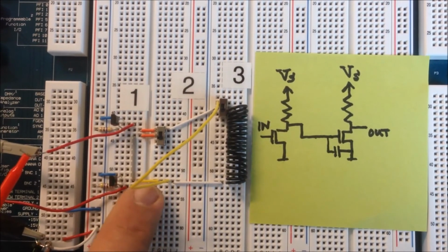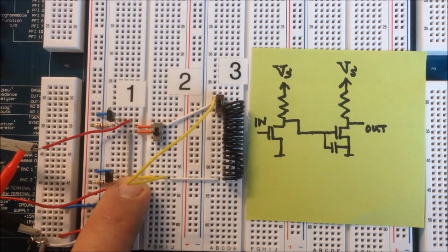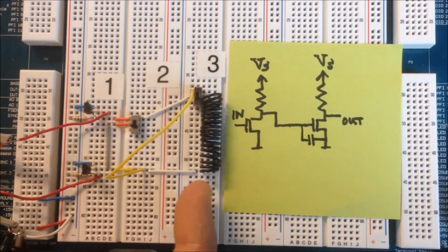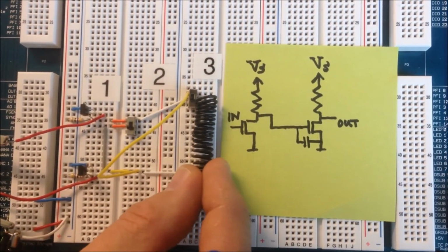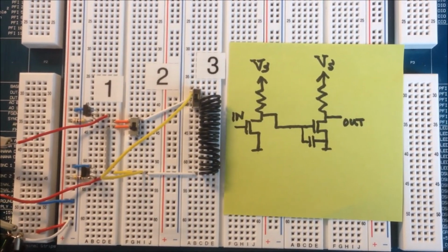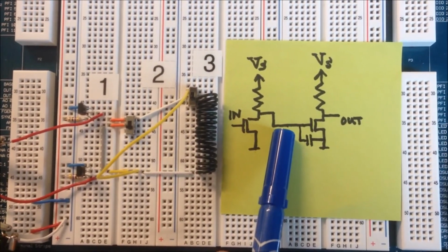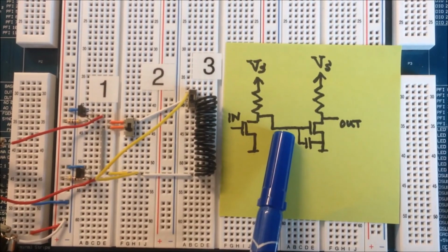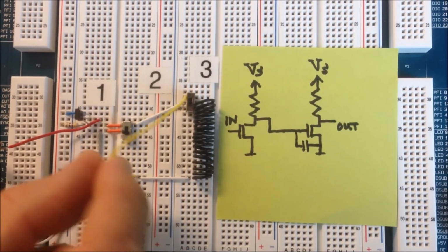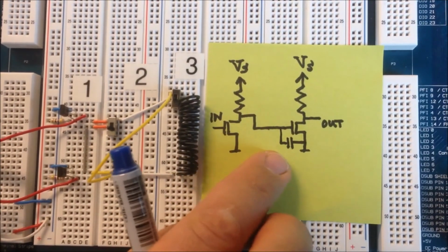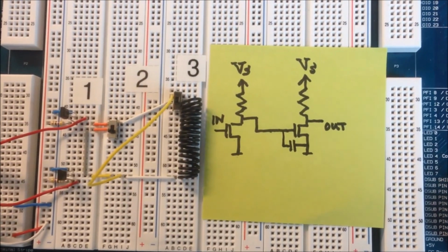Yeah, so what we saw here was that with the short gray wire there was very little oscillation. With this yellow wire there was more oscillation. And when we took this big solenoid we actually saw a lot of oscillation. And the way we interpret this is that this wire here is actually not a perfect wire. It actually has some intrinsic inductance with it, even when it's not wound in a tight loop. And that inductance interacts with this capacitor to give us this oscillation effect.